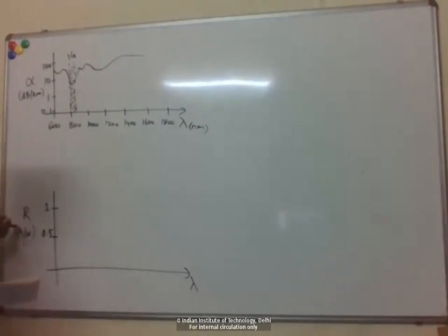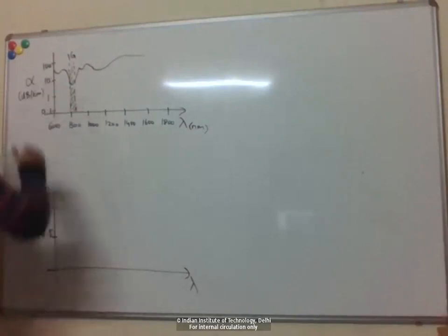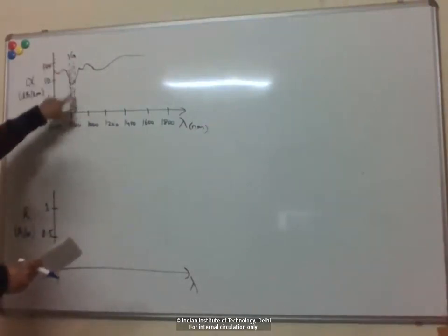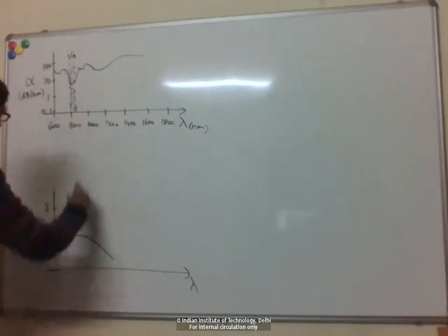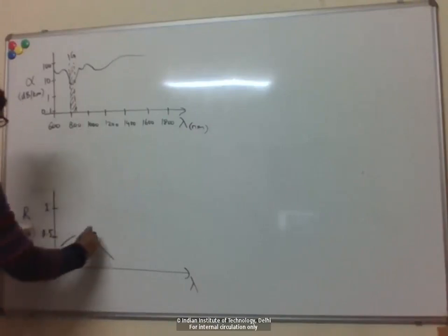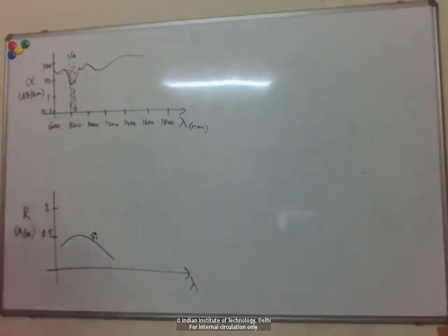This is responsivity, so the units are amperes per watt. That means for a given incident optical power onto the device, it generates a certain current: ampere of current per watt of optical power. The first generation of optical communication systems could work with just silicon technology, because the responsivity for silicon peaks roughly near this wavelength. So for these 850 nanometer wavelengths, one could use silicon photodetectors.